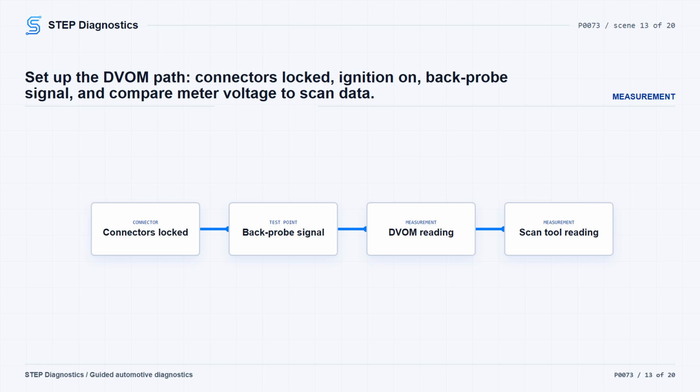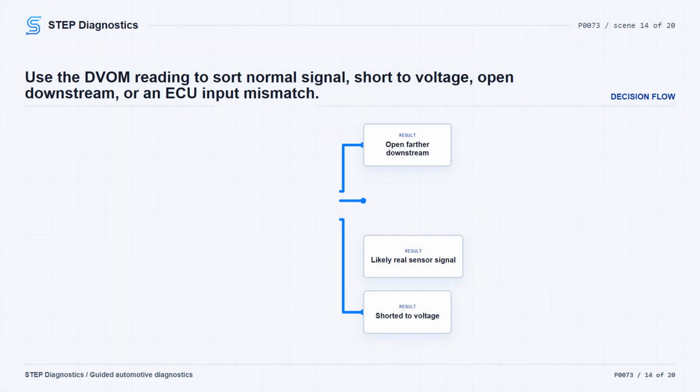When directed by the voltage test result, disconnect the temp sensor and ECU harness connectors and check the temp sensor signal circuit for high resistance and short to ground. If the signal circuit checks good, inspect every connector in the path before making the ECU the call. To check the temp sensor side, move the test lead over and probe the temp sensor ground circuit at the temp sensor harness connector.